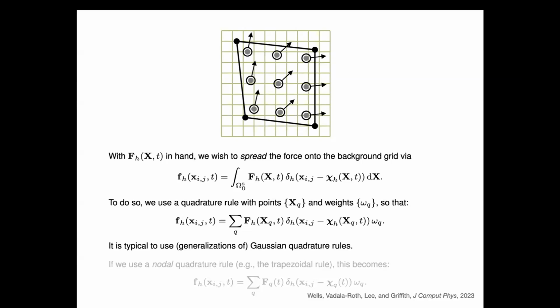No. Most of the work in making these models is making the mesh. If you've got anisotropic material properties, most of the work is coming up with some way to describe the local coordinate systems that determine the anisotropic material response. And then deciding how you want to model the material in the first place. But for most material models, the implementation is a handful of lines of code that looks like tensor calculus computation. So nothing too onerous.